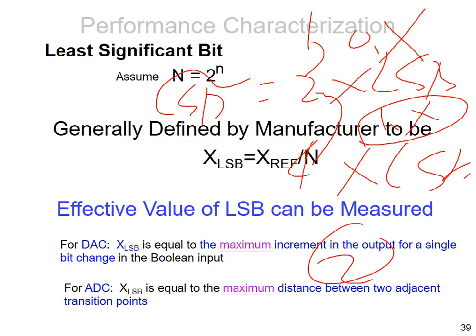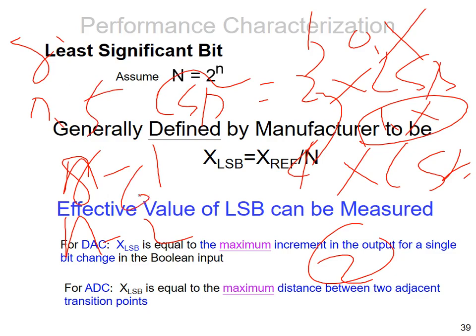So for ENOB, effective number of bits, usually it is not such kind of n-1, n-2. No. It is always, for example, n is 8 bits, right? Nominally, you will have 8 bits for your resolution, but after measurement, you get 7.5, 6.8, totally possible.